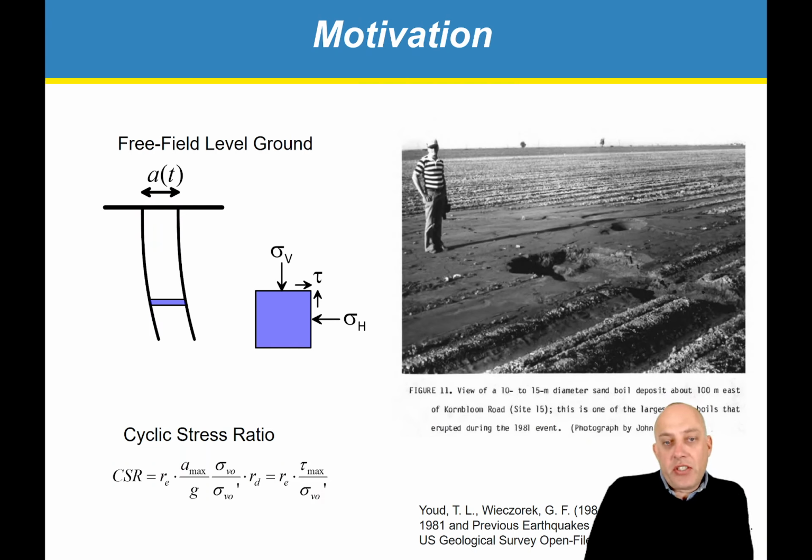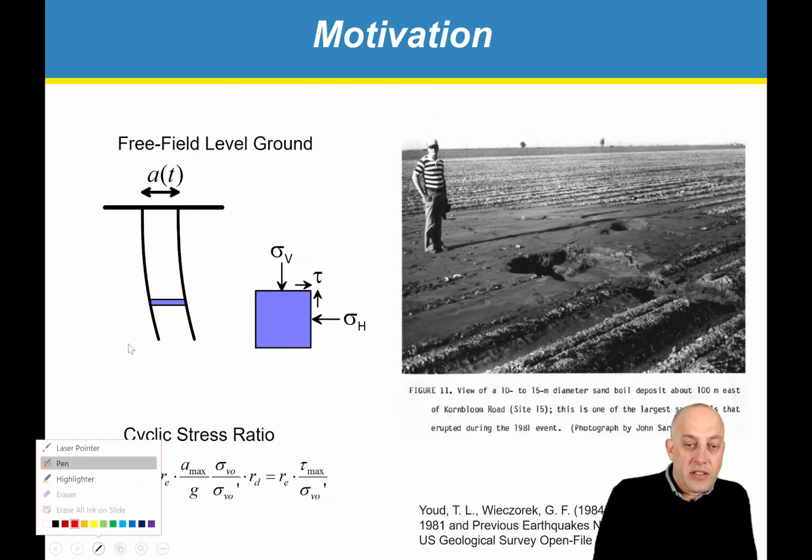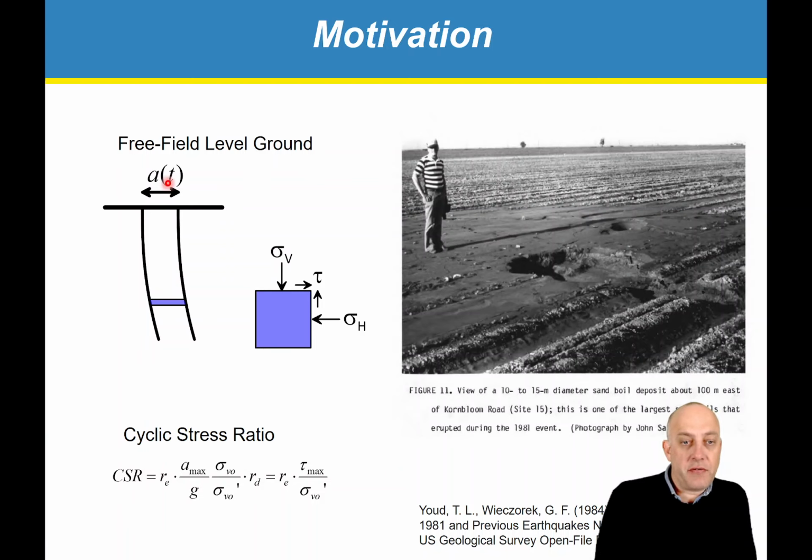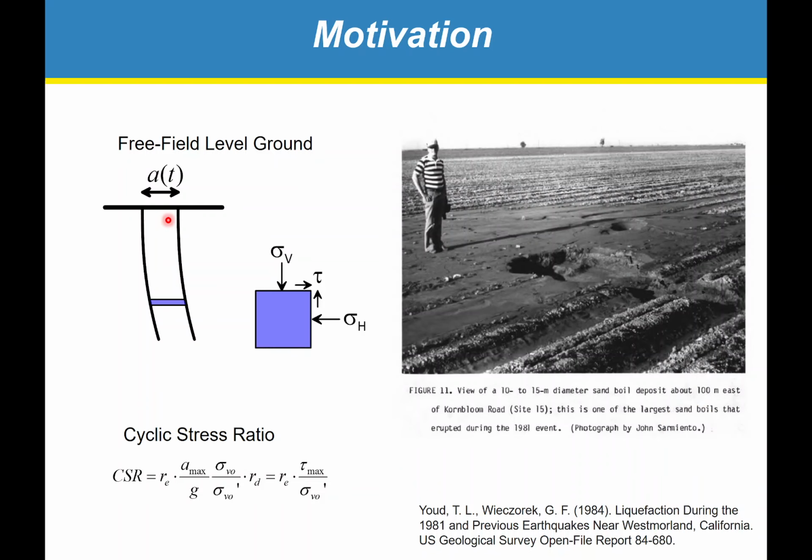So the motivation for our work is that traditional liquefaction triggering and cyclic softening procedures really correspond to level ground free field conditions. So I'm showing those conditions here. So this is showing a free field level ground site with vertically propagating shear waves. I'll turn off my camera here so you can see the citation. So we assume that the waves are propagating up.